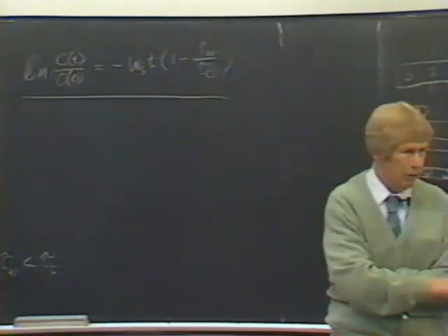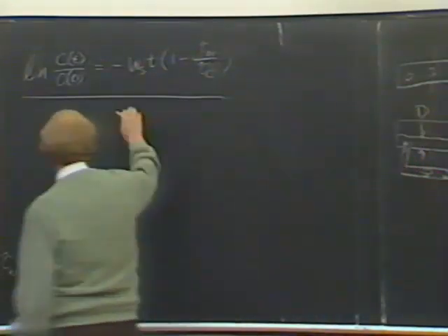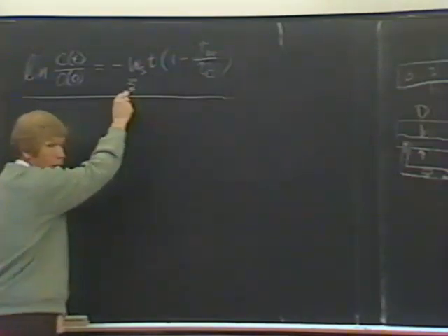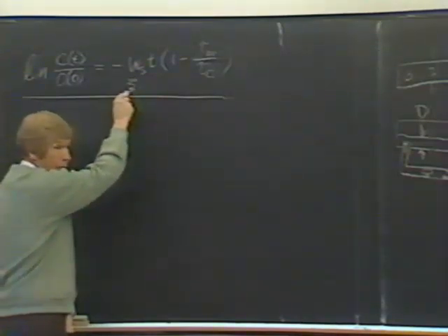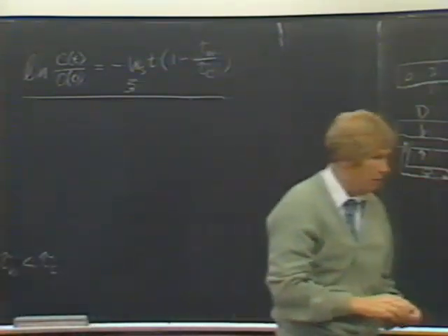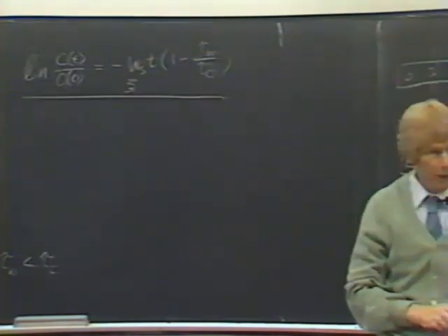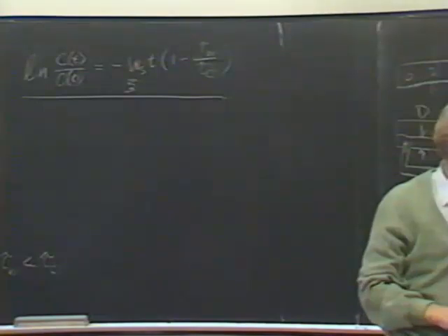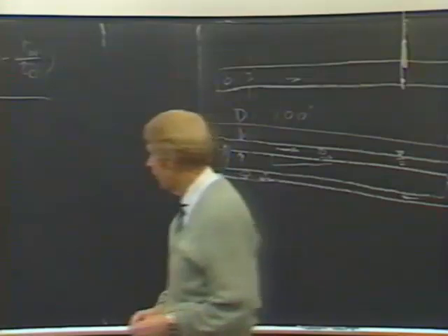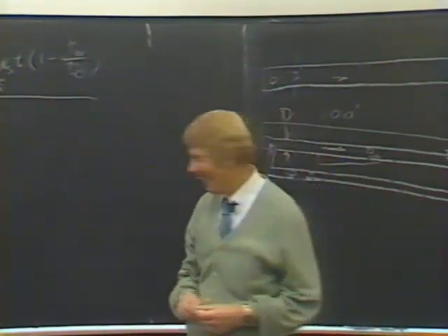Which means it must not have been constant here. And that is supported by the fact that at some concentration this relation doesn't hold, or there's some change up there. So at these low concentrations, particle collisions must not have been a factor. In the system that I described with this recirculation, 12-inch pipe, the settling velocity was constant, or collisions were very infrequent.